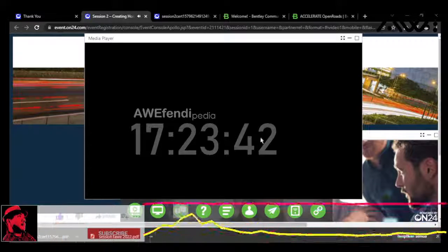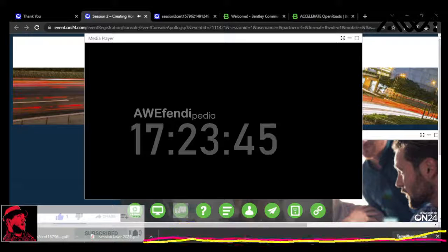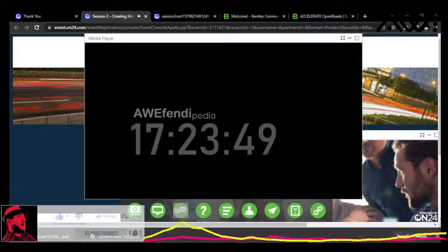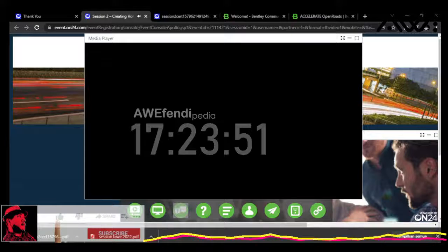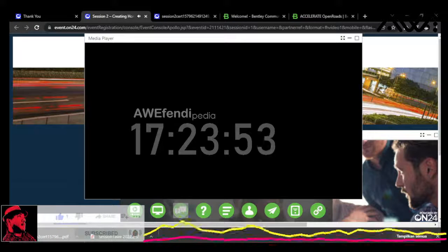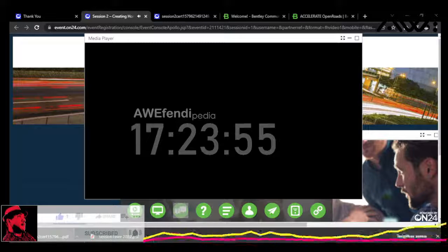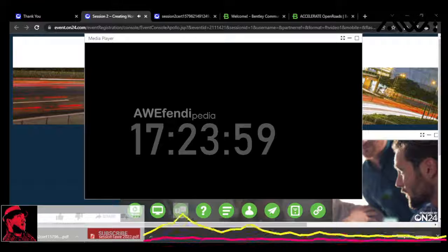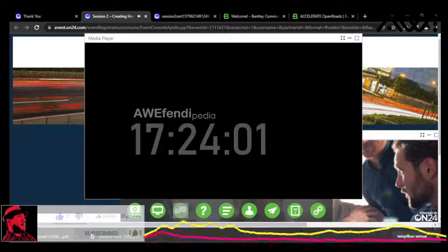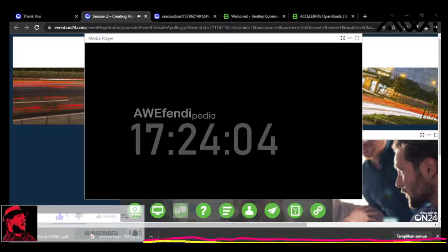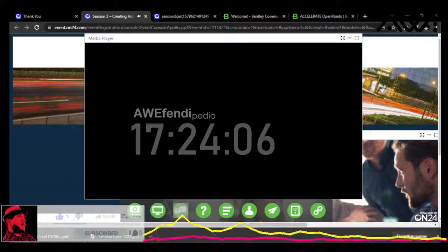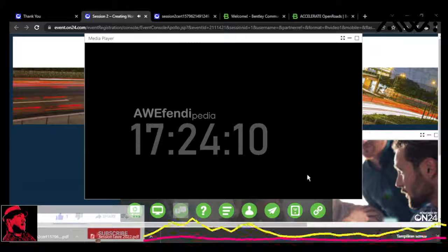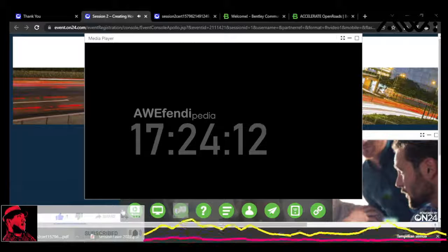I'll hold that radius, and the arc length now is varying. If we go back into our report, if I don't like to key in at this point, I can just cut and paste. So I'm just going to grab and cut and paste out of that PDF. Again, once I place the data in the field, I have to click the tab key or the enter key to lock it. And then I'll data point one last time to place it. Notice it's prompting me now to trim or extend, which it's going to do every time I place this.